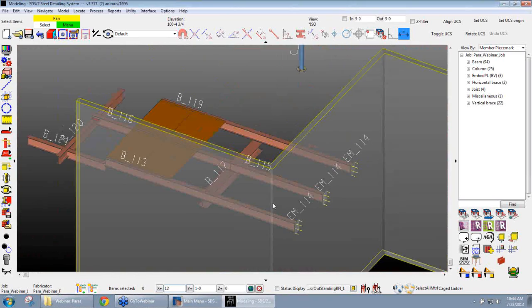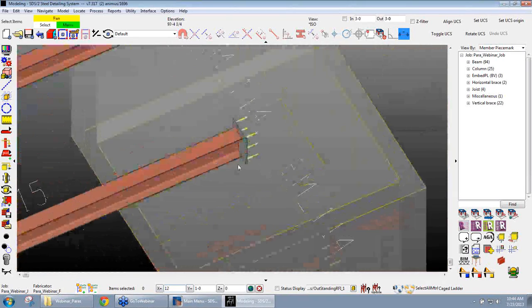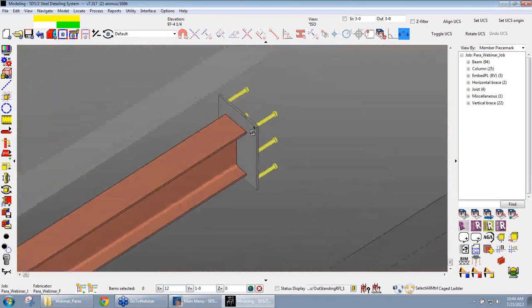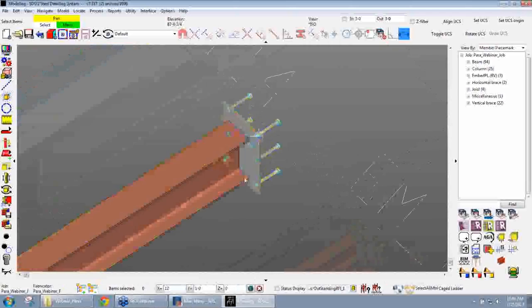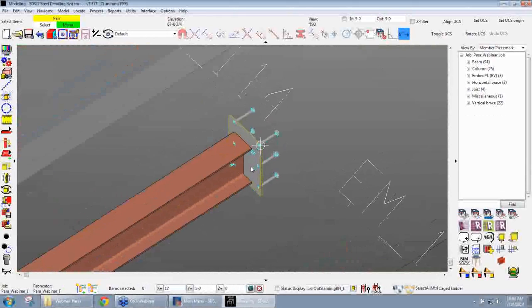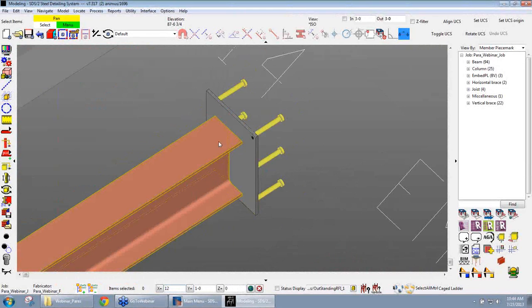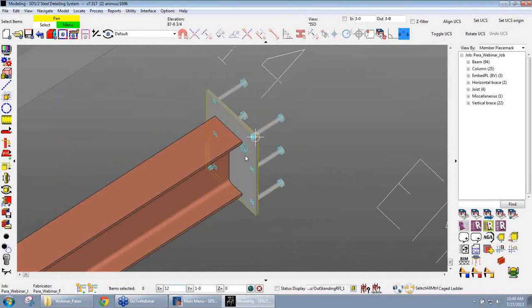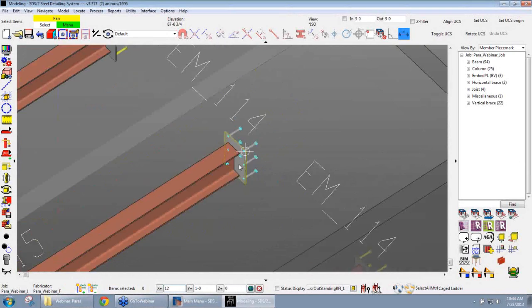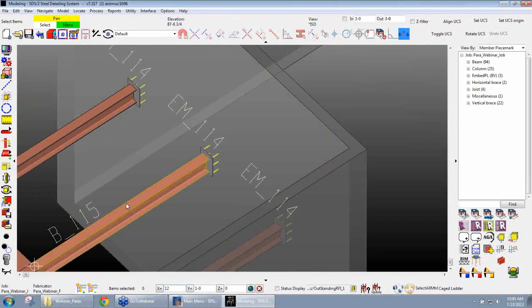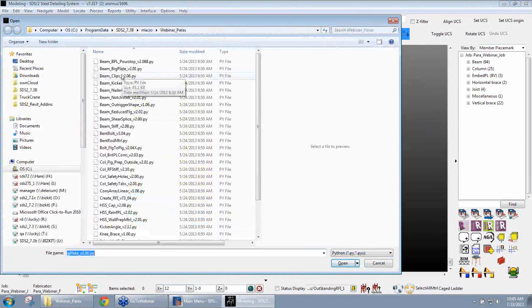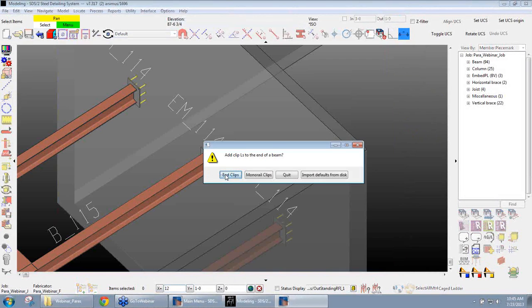Moving on, I've got a beam clip. So another similar scenario here. I have a beam framing into an embed plate into a concrete wall. I need to go through and add in a set of clip angles here that's going to weld onto the embed plate. So I'm going to run a parametric. In here I have another one called beam clips. I brought up the actual Python file of that earlier. Like I said, in this scenario, I'm going to add in the end clips.